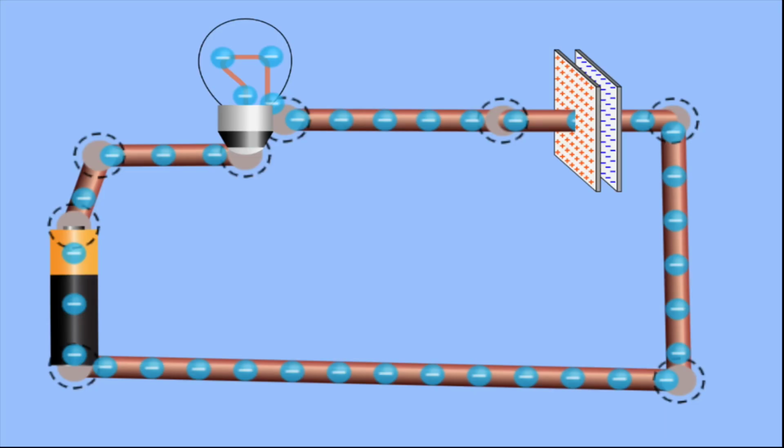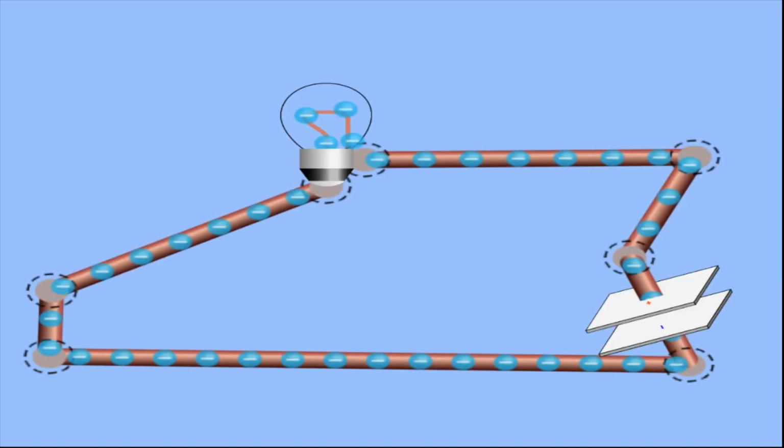For our second experiment, we wanted to see how the light would react when we attach it to a circuit with a battery and a capacitor. We found that the light began to light up for 6 seconds as the electron current flowed through it, but once the capacitor met equilibrium, the light began to vanish. When we took the battery away, like we did here, it lit up again as the electron current flowed the other way until the capacitor reached another equilibrium point.